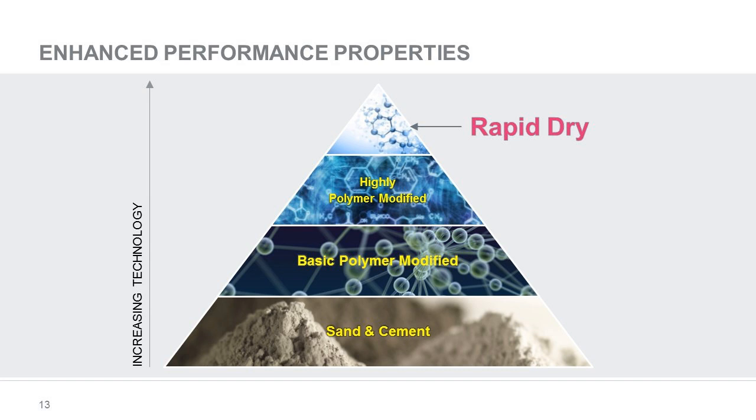We may need less water staining on a trowel or need to reduce the risk of warping, so we use a rapid drying technology or an epoxy. We may start with a standard mortar but realize that we need more flexibility due to thermal expansion when troweling onto heated slabs. Ultimately, we may have even added all of these elements, but we want to deliver fail-safe technology and strength, so we add additional elements and develop unique fiber-reinforced adhesive performance.